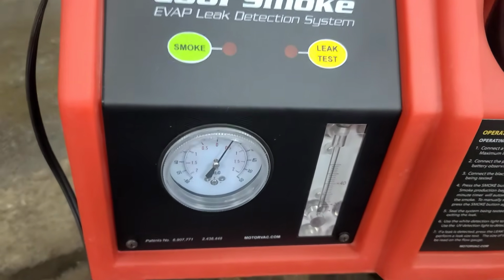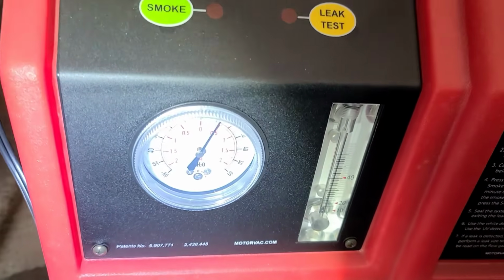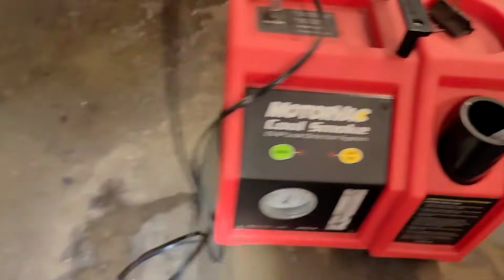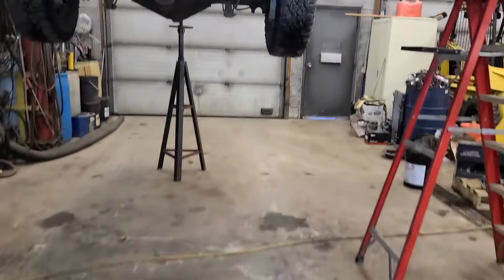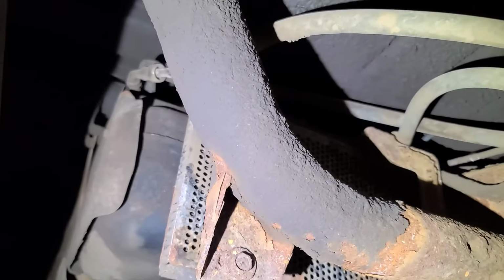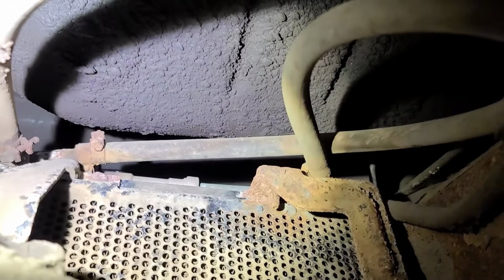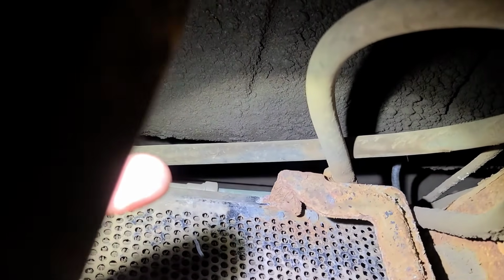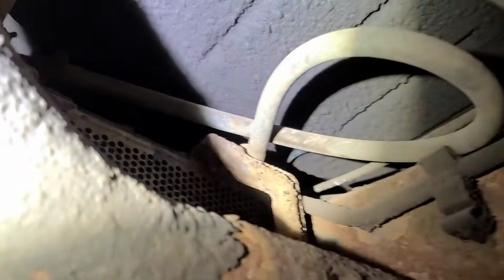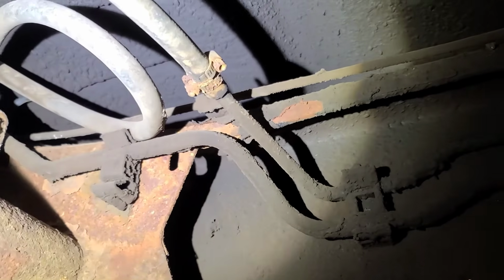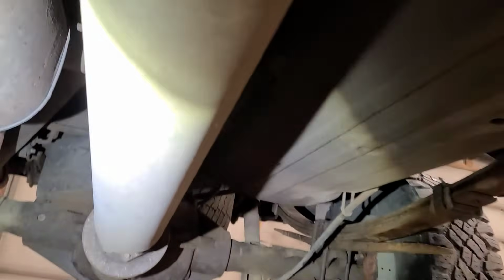So the line is holding roughly 12 inches of water, which is about a half a psi, and there's no obvious leaks anywhere that I can see. Now, unfortunately, this is a positive pressure on the line, and it could have a leak even at that seal there on that connection right there, and it leaks under a vacuum. So nothing obvious, that's for sure. And no signs of fuel. When I blew the fuel back, there's no signs of fuel.